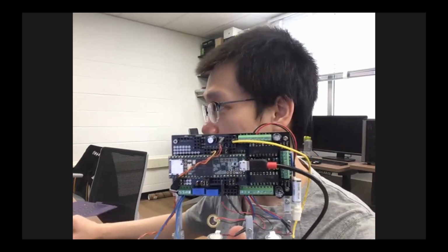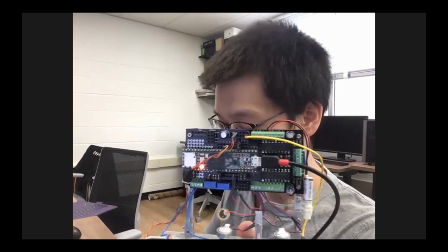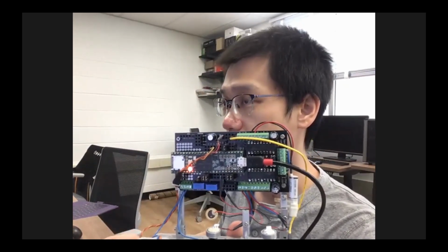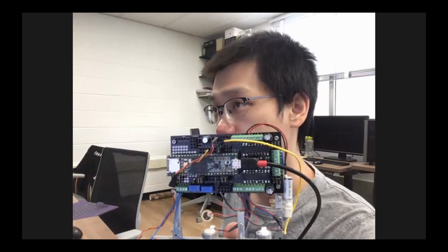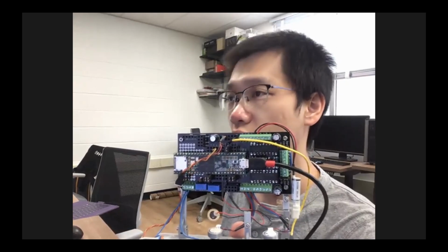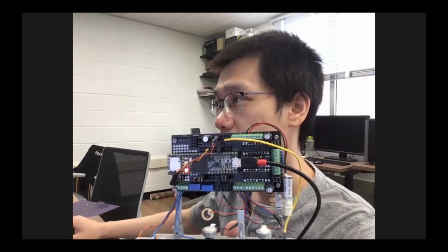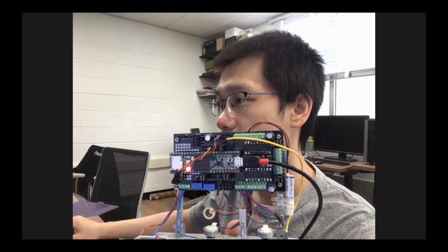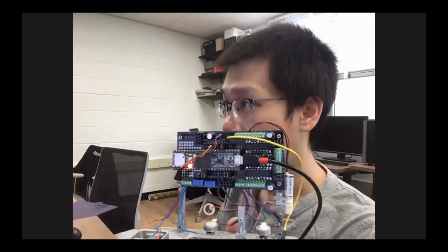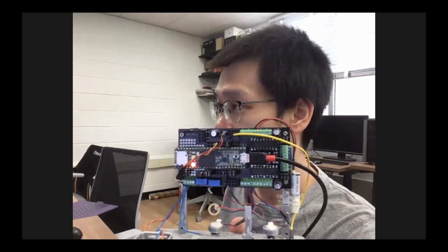And then I'll just try the on off duration. Remember, this command requires 2 following numbers. So basically, we are assigning the on duration and off duration in one command. And here I'm using 100 milliseconds on and 100 milliseconds off, so it's supposed to blink 5 times a second. Yeah, it's doing that. And then lastly, I will just write pause 5 sec and hit enter.